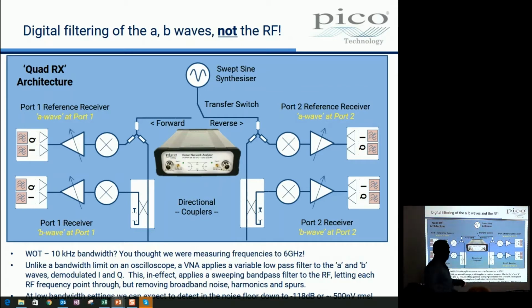I don't want to make things overly complicated, but yes, a VNA or a frequency domain product, a spectrum analyzer, is the same. You can have a 1 hertz filter on a spectrum analyzer, and it just makes the frequency much sharper. We must have the same content on the FFTs, mustn't we, as the resolution of an FFT changes. Well, the FFT increases the sample window. Yeah, which is effectively what the filter's doing, isn't it?